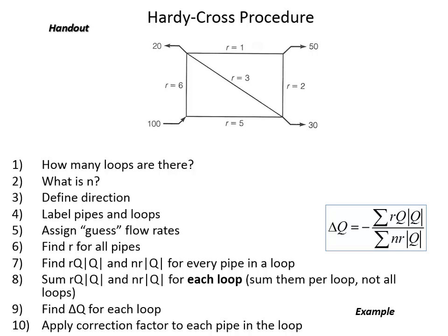Okay, so the flow rate I'm going to use is 47.332. And pipe 1, 3, I'm going to go over here. This is the most recent guess, but I need to flip the negative sign. Because when I'm working in pipe 1, 4, I have a different sign convention than working in loop 2 than in loop 1. So what I put here is going to be 1.343. And then for pipe 3, 4, I'll just use this negative 52.668. And then I can go through the same thing over and over.